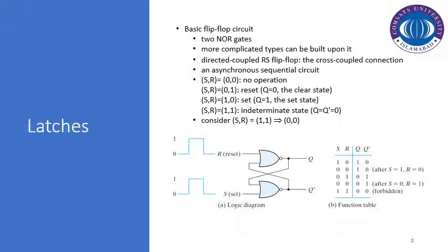For latches, the output depends on the input, and any change in a specific input can change the output. So latches are level sensitive devices. The change in the levels of the input is responsible for the change in the output. Flip-flops, on the other hand, are edge sensitive devices.